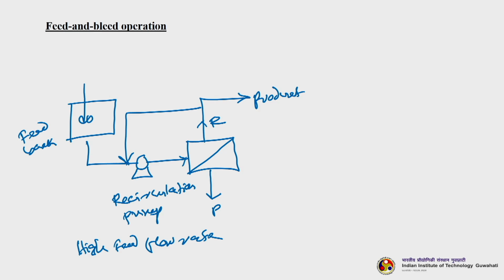Okay, the part of the retentate is being fed back to the loop just before the recirculation pump. Okay. So, that means what is the major thing it is happening here? Volume of product that I am taking out, right. So, that is this much, and the volume of the retentate that is being again recirculated here are the same.